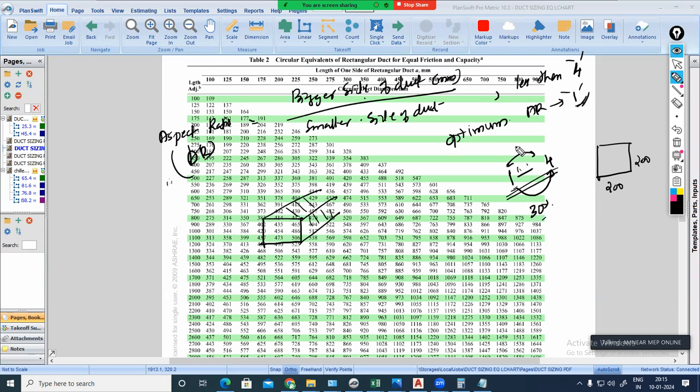The second thing, the duct we are proposing definitely needs thermal insulation. Correct. On the full outside we provide thermal insulation. So duct heat gain means, from higher temperature to lower temperature, the duct will be getting heat, no? That we can prevent up to a certain extent. But no thermal insulation is 100% efficient, right?